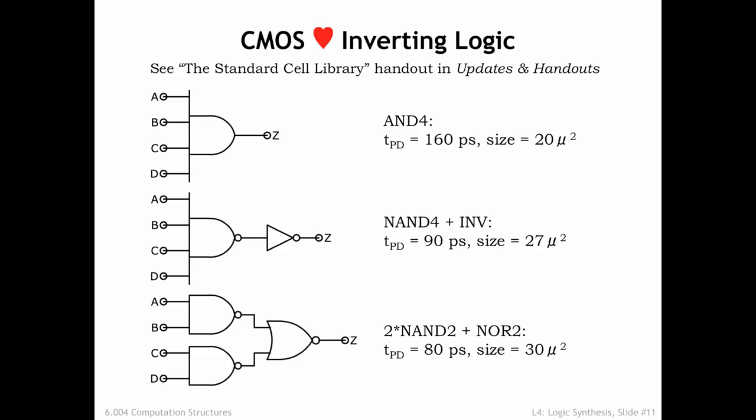Why would we ever want to use a slow gate? Remember that the propagation delay of a circuit is set by the longest path in terms of delay from inputs to outputs. In a complex circuit, there are many input-output paths, but it's only the components on the longest path that need to be fast in order to achieve the best possible overall TPD. The components on the other, shorter paths can potentially be a bit slower, and the components on short input-output paths can be very slow indeed.